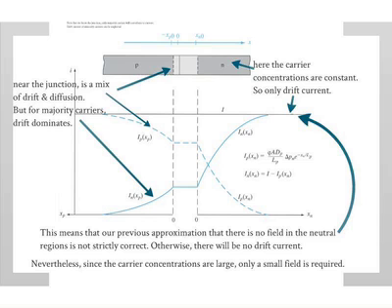Which basically says the electrons supplied for recombination with the injected holes and the injection of electrons across to the other side. Okay, there are two things happening, right? So keep that picture in mind. So what do electrons do over here? The electrons have to recombine with the holes, right? So those electrons have to be supplied from the battery, like I said. But also, electrons get injected across, right? So there's carrier injection to the other side as well. You have two terms, so that's the carrier recombination and the carrier injection. And when you subtract this, you'll get those two terms. So this is the expression for that.